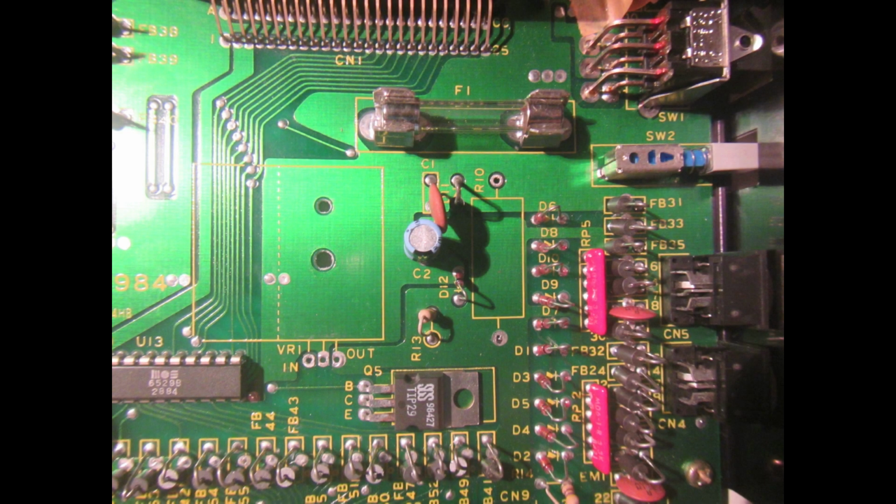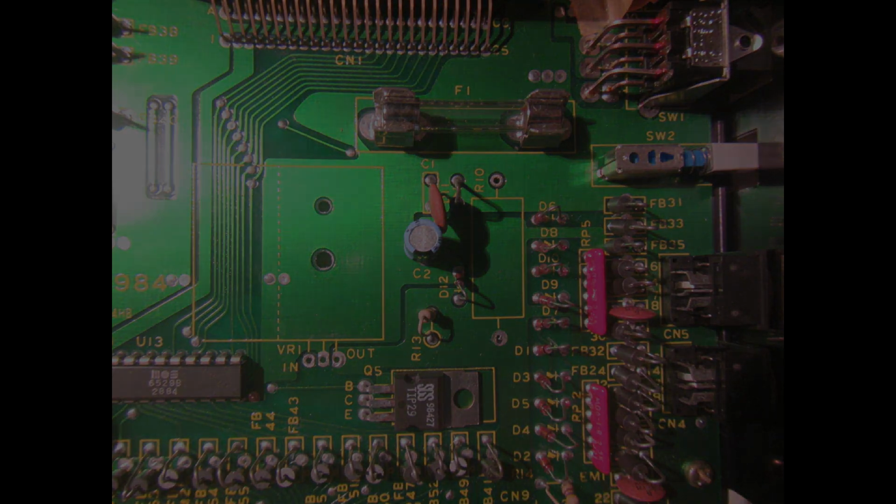I've decided to remove both the 7805 and the resistor and use a switching regulator of some sort in place of the heat-making duo. While waiting for a suitable regulator, however, I can power the C16 directly from a 5 volt DC supply.